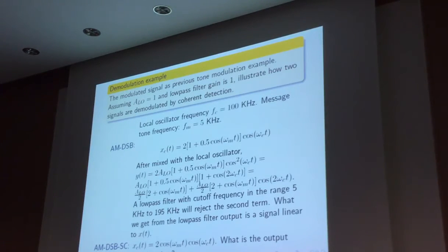Okay, so we learn about how to design a Butterworth filter, of course passive Butterworth filter, right? So for passive Butterworth filter, we always study from the low pass prototype. No matter in the end, the filter you want to design is a low pass, band pass, or high pass, you always study from the low pass prototype. Okay, but low pass prototype means that the cutoff frequency for low pass prototype is 1 radian per second, and the matching impedance is 1 ohm. Okay? Then we can come up with the two configurations, pi type and T type.